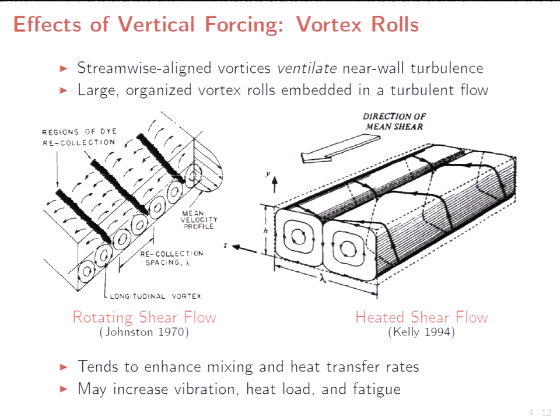If there are these vortex rolls taking the hot fluid above the wall and bringing it near the wall, then that can cause the blades to become scoured or melt, and patches like that will occur. But you can also use film cooling, where you effectively generate streamwise vortices near the wall rather than in the large-scale flow, where cool flow is injected along the wall to counteract that effect.